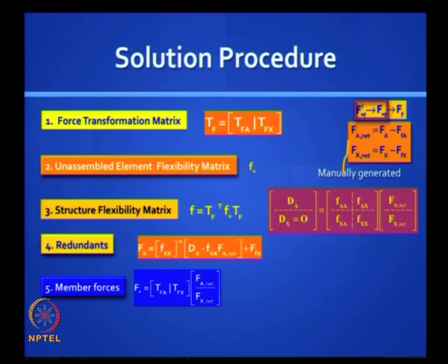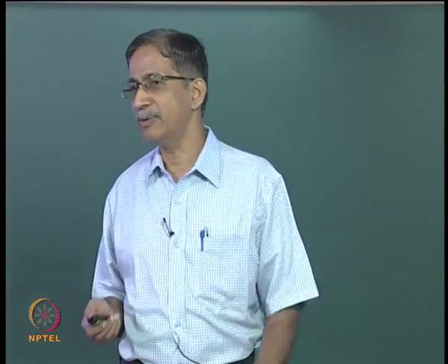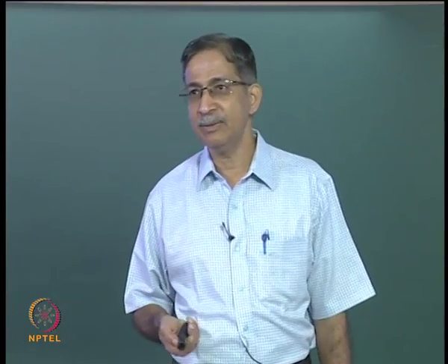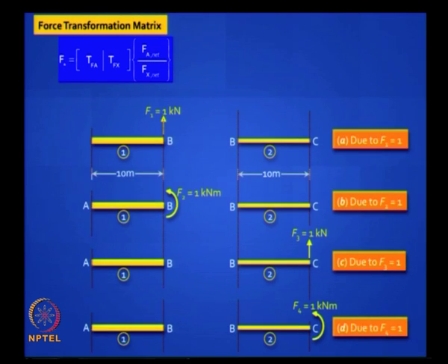And in this case we are only interested in the shear force and bending moment diagram, and find the membrane forces directly by using the force transformation, where you have to put in the correct values of the net load vector. Okay. Joint displacements you can get also this way, dA directly. Okay. Now let us do this together.